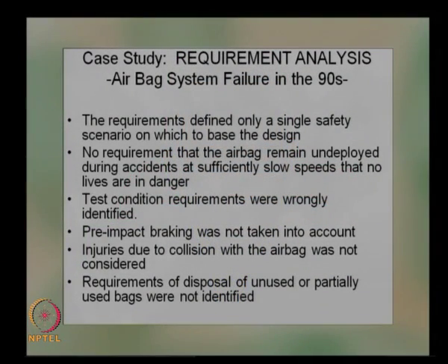Third, the test condition requirements were wrongly identified. Again, the conditions under which the airbag was to be tested for safety were wrongly identified. Here a dummy driver with a weight of around 70 to 80 kg, sitting in an upright position with the hands at 9 o'clock and 3 o'clock positions, driving at a speed of 30 miles per hour, having a head-on collision where the forces are always straight on the front of the car. Only this scenario was considered for testing, and in most cases this was not the condition, because it's not always a head-on collision.